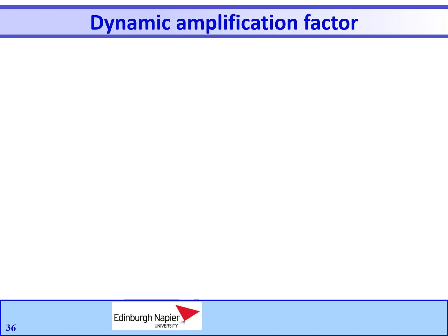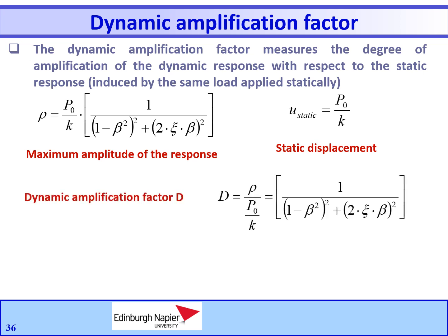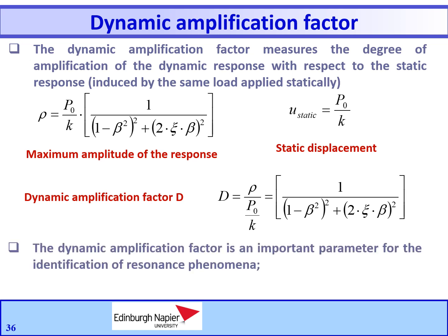Having solved and commented on the solutions of the equation of motion, and having defined the maximum amplitude of the response as well as the static displacement as a function of P0, we are now defining the dynamic amplification factor D that measures the degree of amplification of the dynamic response with respect to the static response as induced by the same load applied statically. The dynamic amplification factor is an important parameter for the identification of resonance phenomena.